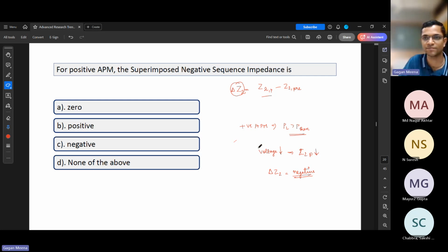Is this clear? Normally our understanding is, say the load is more than generation. We divide load into active and reactive power. If active load is more than the active generation, then it would contribute to a frequency change. And if reactive power is less than the required, then it would contribute to the voltage. Is my understanding right?